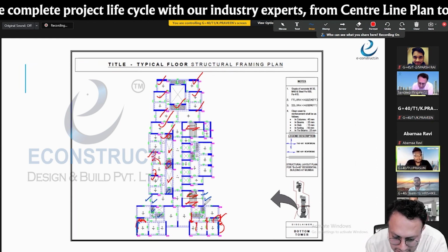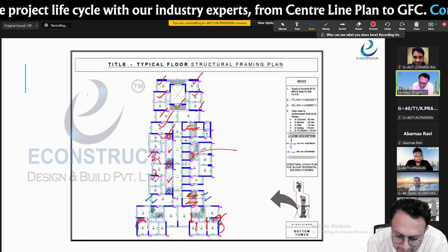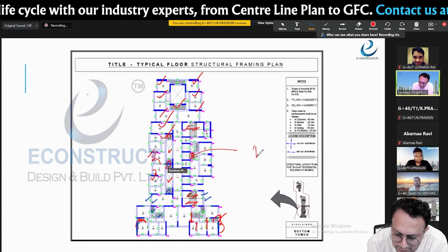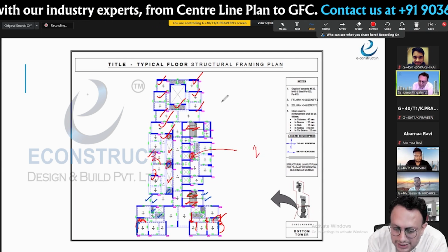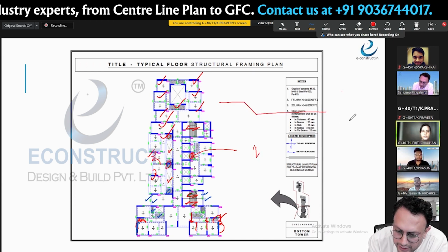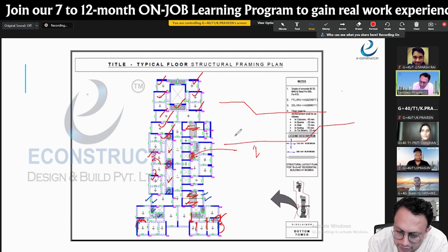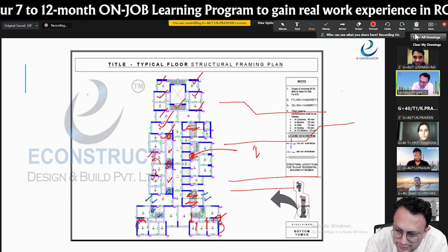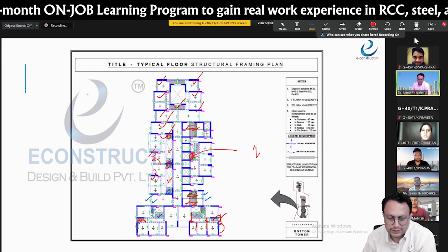And the small slabs do not give the one-way slab, two-way slab. You can give that as a one-way slab enough. So two-way slab means on the side you need to crank it. Another bar will be like this, and you need to do this. One way means you go straight bars, so it is easier, at least.